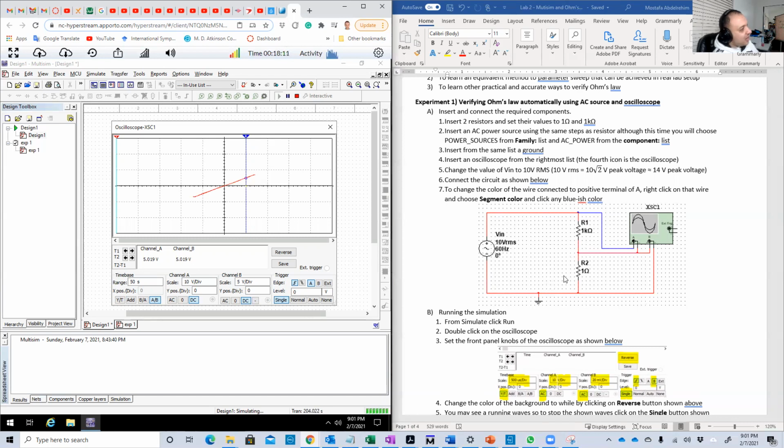Okay, but maybe in your lab experiment, I mean in a practical setup, 1 ohm is a very small value. This might cause the current to be very high, and that may, for example, damage something, or exceed the maximum rating for some of the components in your circuit that cannot handle such high currents. At that time you might need to put a higher value of resistor. And in that case, you still can do the parameter sweep, but you should take care of that conversion, because now V doesn't equal I directly. No, I is equal to V divided by the value of R2.